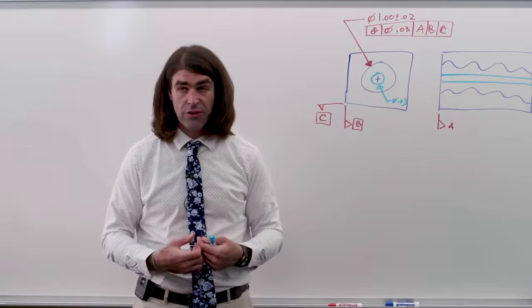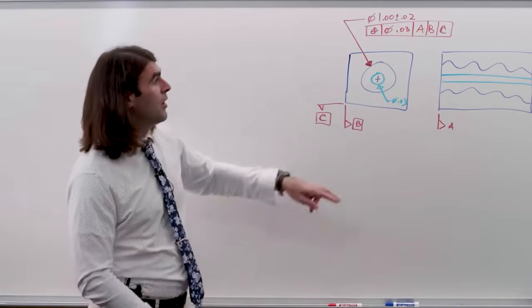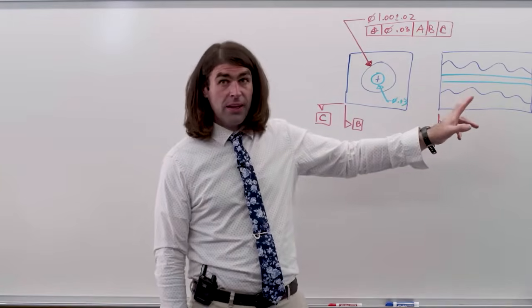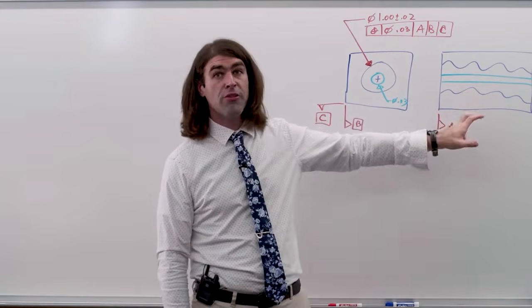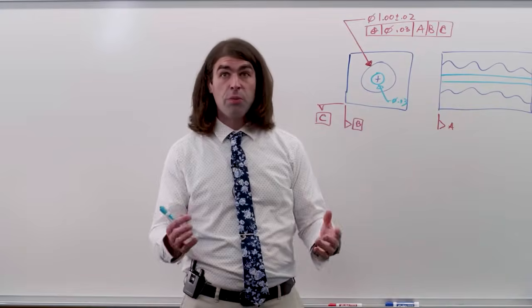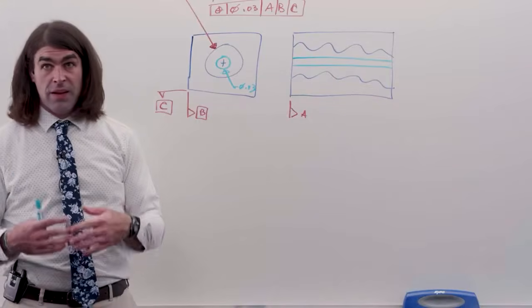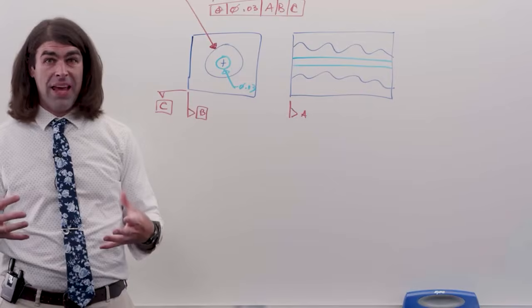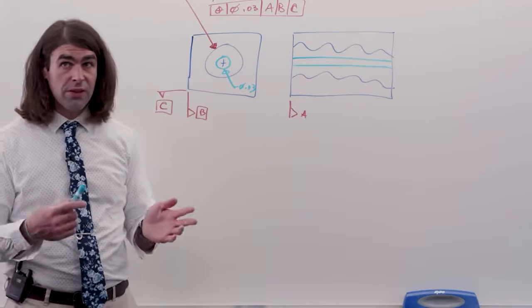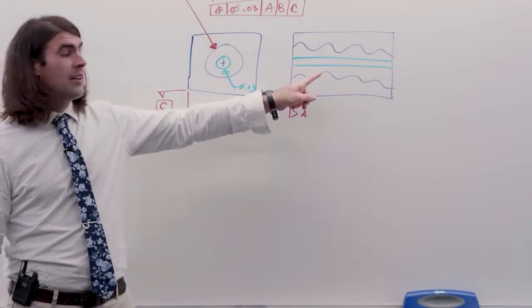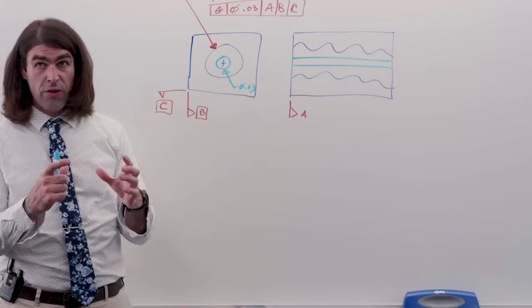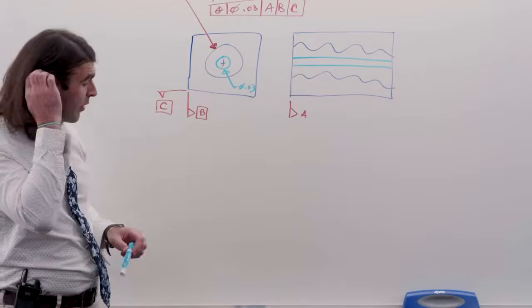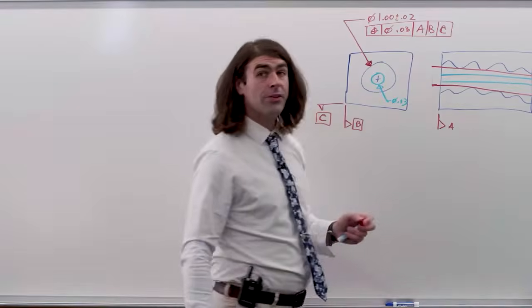It's the largest similar feature that will expand within a hole, or the smallest external feature that contracts around an external feature. So in our case right here, how it's usually done is you go through gauge pins until you find the largest one that will fit through the hole. If it's a large bore, you might need something like a mandrel that actually expands into the hole. But essentially what you're doing is trying to find a best fit with these high points and then the largest cylinder that will fit through there. So you'll end up with something like this.